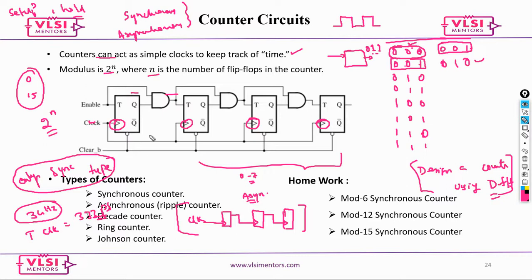So you can ensure the data operation between these two can be within 333 ps. But in the asynchronous case, you have no idea how much time it is going to take. Static timing analysis, STA, supports only synchronous circuits. For asynchronous, we don't have a methodology to say this will work at 3 GHz.